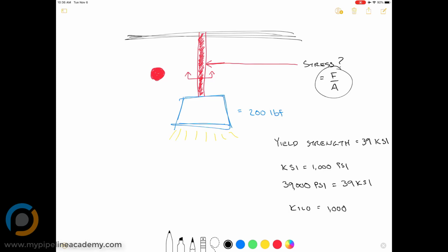Some of this is kind of up to us. Let's impose some restrictions on ourselves and just see what happens. Shall we solve for the point at which our aluminum rod will fail? That will be based on the diameter of the rod, and then we'll know the diameter needs to be at least that big. Is that how you would do it in real life? Well, it depends what they're asking you. If someone gave you a radius and asked will this fail, you could solve it directly. But as of yet, we haven't given ourselves a radius. We could do it that way too, though. Let's do it the easiest way first.